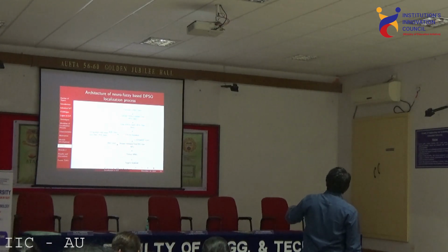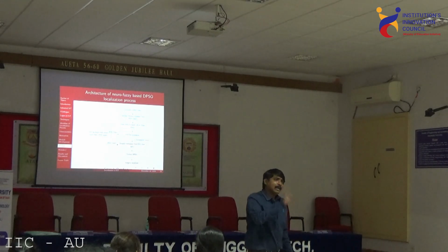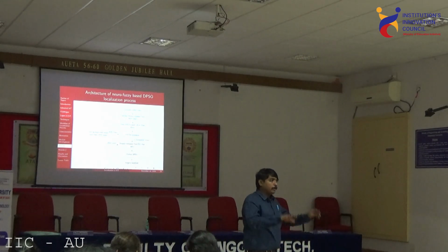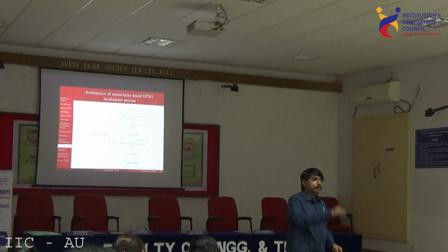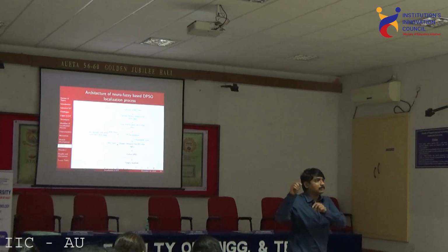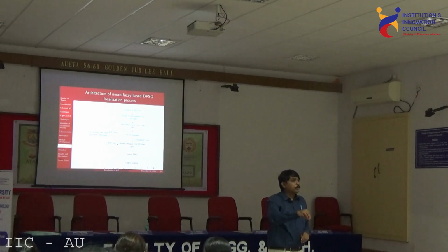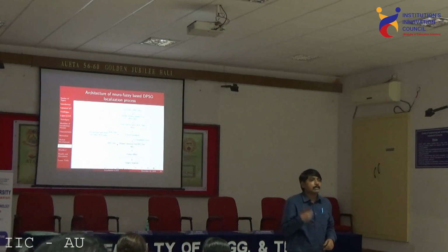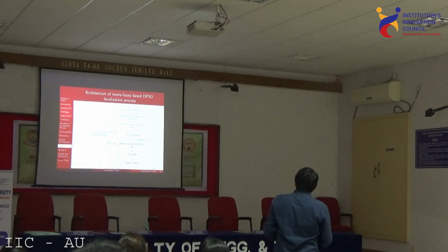During my training phase, I will be collecting different RSS values and different D values, and I will try to model: if I set up this network on a mountain, this is going to be my noise, so whatever D you get, add this noise. If you set this up normally in a closed room, this is going to be the noise. So it is something like training I do prior to implementation. Prior to implementation, I estimate all of this and try to find the fuzzy rule.